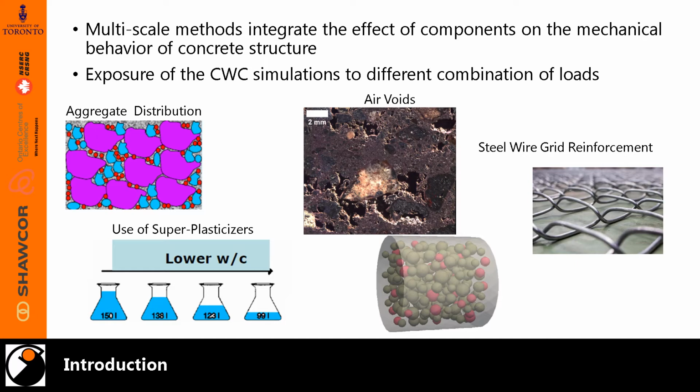The compressive strength and the Young modulus defined in the standards are not suitable for these unconventional concrete mix designs. Using the Young modulus and the compressive strength as the only parameters is not enough. We want to define the full stress-strain curve to predict the behavior.